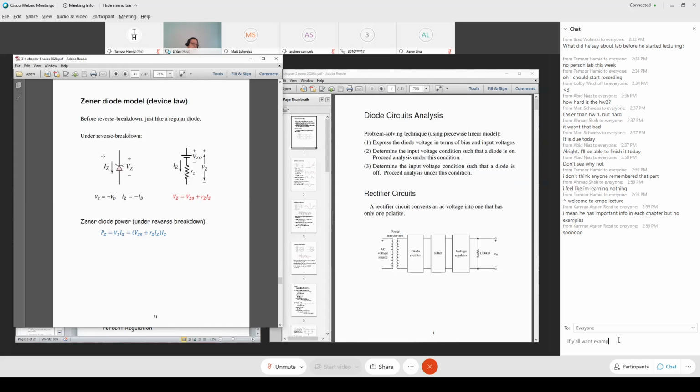So this IZ is the same as this IZ, and this full Zener voltage is VZ here. Sorry, that just surprised me that we're using that as the non-ideal, because voltage sources and resistors are linear and Zener diodes are non-linear. So when it said non-ideal, that confused me. No. This non-ideal Zener diode refers to RZ being non-zero.